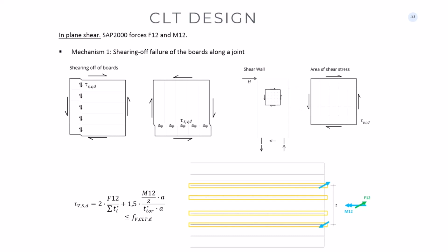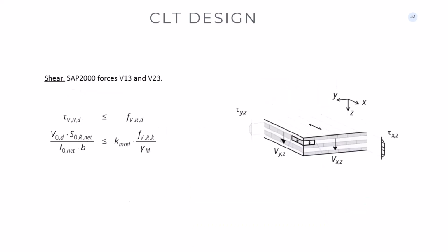It's the same thing that you notice in a composite structure. You have a tension steel member, a compressed concrete, and you have a shear in between that normally you take with studs. The same thing happens here because you have 5 lamellas, and unfortunately very few producers, almost none, glue this part. So they are glued on that surface, but not on that surface. So the lamella, when you apply the movements, can roll like that. And this is called roller shear.